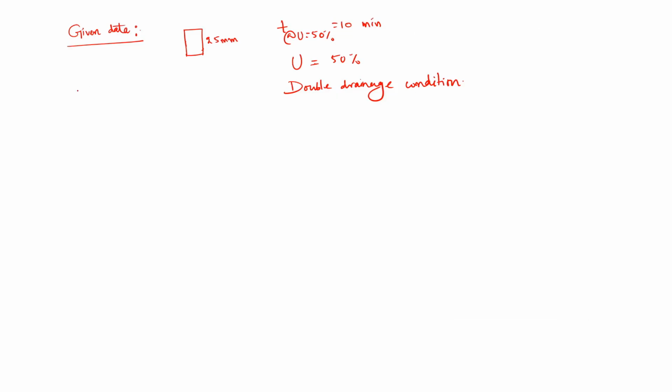So yeah, now see, let us say this is the clay layer. Okay, now when there is consolidation happening, suppose this is sand, this is rock below, and this is sand above. Whenever we are trying to consolidate by applying pressure, the water existing in this clay tries to go up, because sand allows water to drain out, whereas rock does not allow.